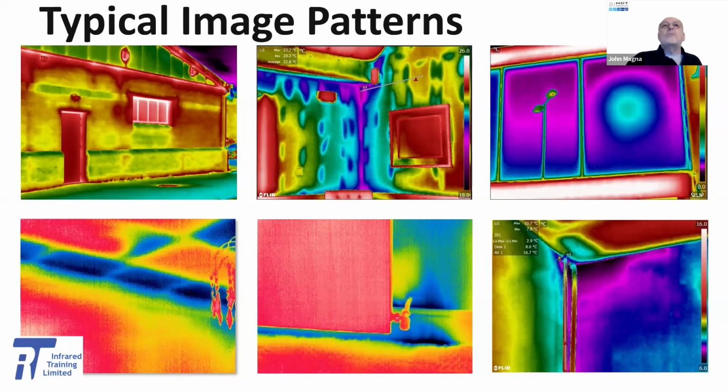But although it's often combined with small leakage areas at joints and penetrations, this condition will typically not show up with an air permeability test result, but it can give rise to considerable performance issues. Top right, we have an external image of a failed gas seal in a double glazed window unit, identified during a handover survey. Bottom left image, this is a cold roof construction, wall to ceiling junction at the eaves. And the geometric dark blue shapes we can see is the area between the ceiling joists where there's missing insulation. We can also see that there's an area of misplaced insulation, which is not in good contact with the plasterboard.